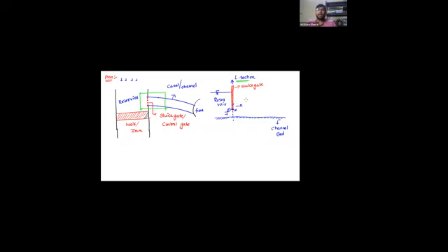so then the flow parameters are going to change with respect to time. Such a flow is known as an unsteady flow. In simple words, you take a particular section, if the flow parameters remain the same with respect to time, we call it steady flow. And if the flow parameters vary, we call it unsteady flow. Okay.